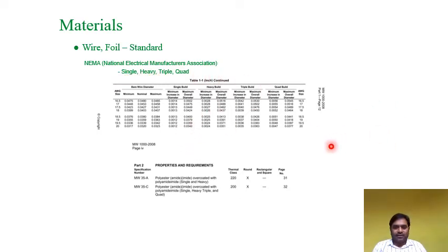More details you can find by downloading the magnet wire data sheets, which have the electrical specifications in detail, and this is how they define magnet wire 35A, magnet wire 35C. So what kind of coating they have used, polyester, polyamides, what is their thermal class, and what is the size, whether it is round or rectangular, or a foil. Different types of winding materials are used for different designs, and it is up to the designer how he wants to choose the conductor.